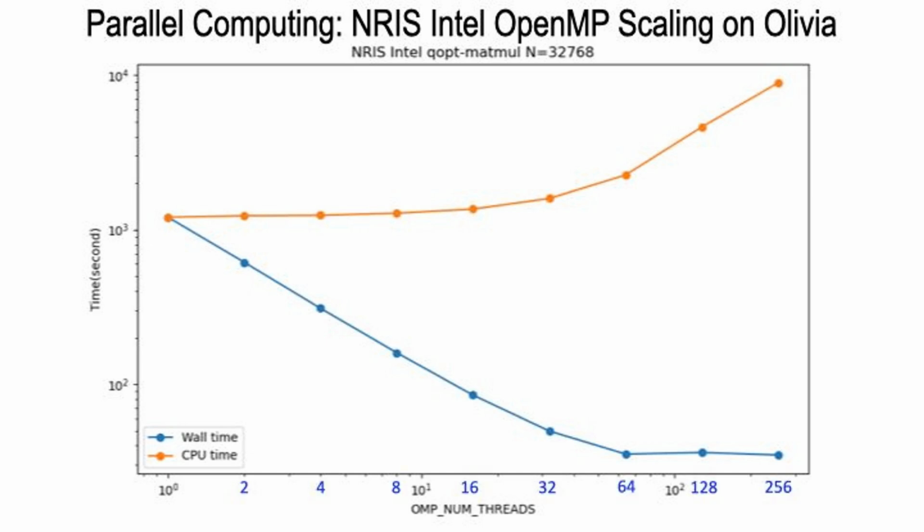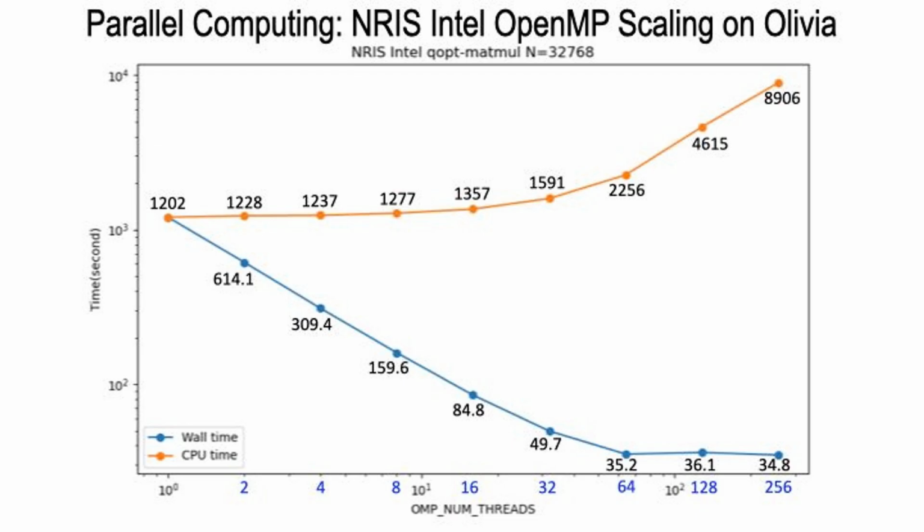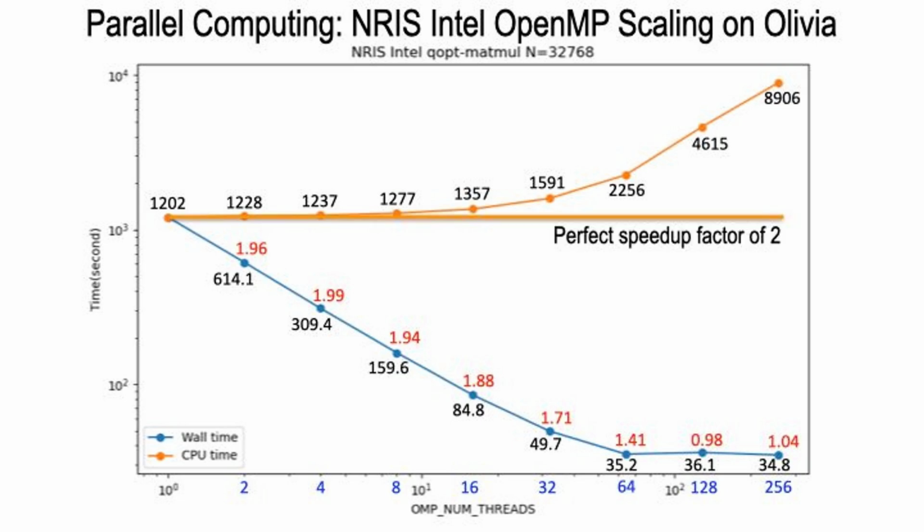Let me first enter the number of threads or cores used in the scaling analysis. I can add the mean wall times to the figure. I will also enter the CPU times, calculated by multiplying the wall times by the number of cores used. Finally, I include the speedup factors between tests. The CPU time was plotted to show that, in an ideal scenario with perfect scaling, the curve would form a straight line, reflecting a consistent speedup factor of 2 across all tests.